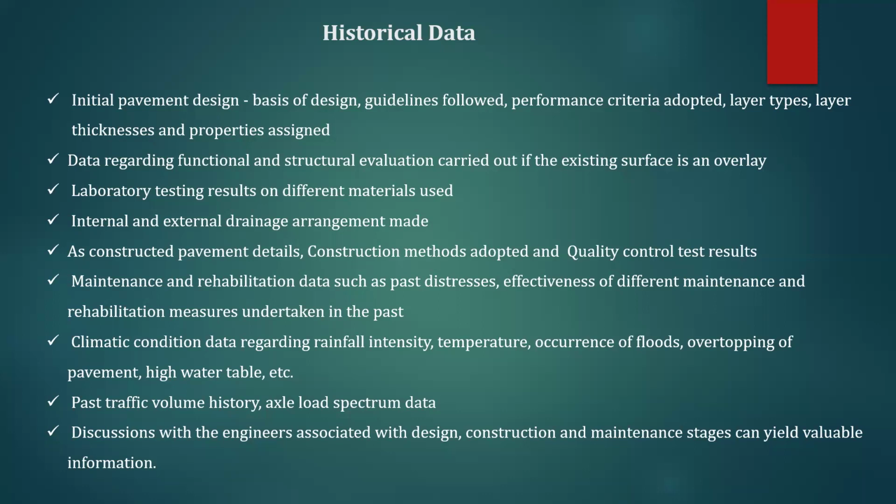What is the classification of the soil, whether it is clay, sand or silty sand you used, what is the CBR value, what is the plastic limit? Because a flexible pavement or bituminous concrete pavement is such that if you have some sort of volumetric difference in the bottom layers, it will reflect to the top of the pavement surface. For that reason, soil is going to be a very fundamental material. You have to have a thorough understanding of the liquid limit, plastic limit and all that. If you have a high plasticity index, definitely the failures will be different. So understanding the failures is very important.